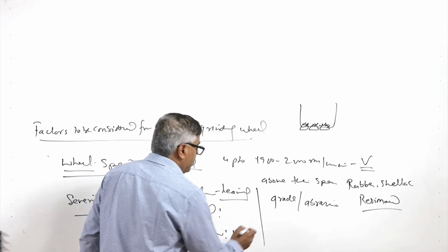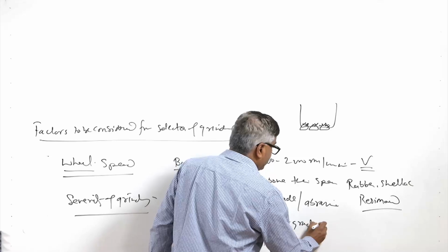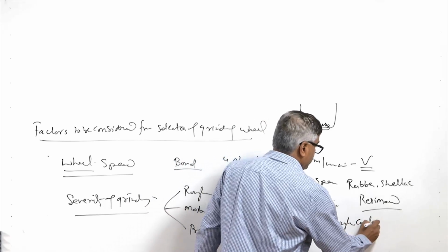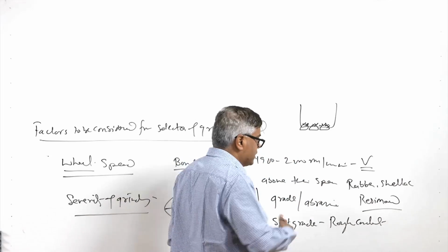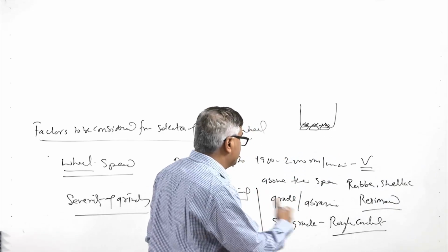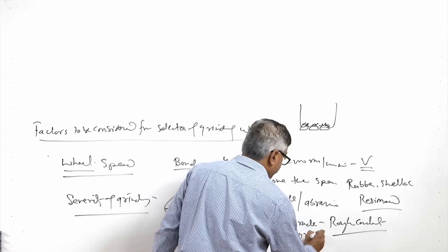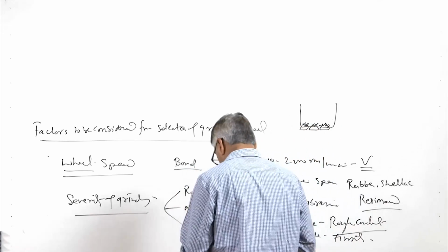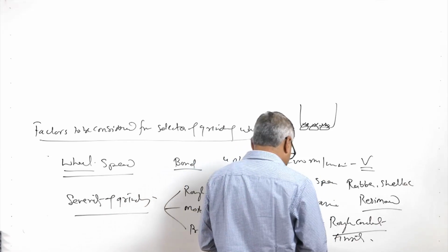Normally the soft grade is selected for roughing conditions, so that the abrasives keep on breaking and producing fresh cutting edges in order to have good cuttability and good grinding action, while the hard grade is used for finishing and precision work.